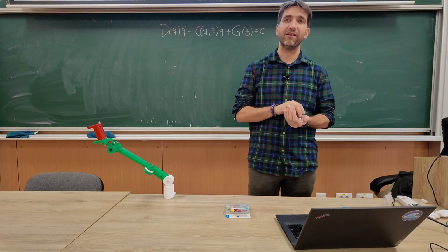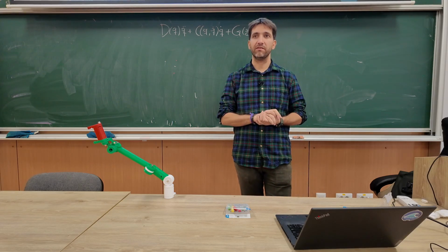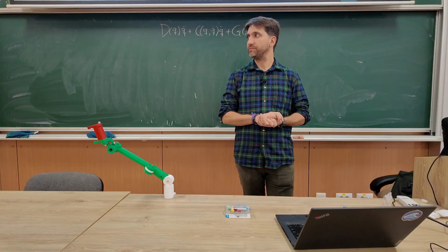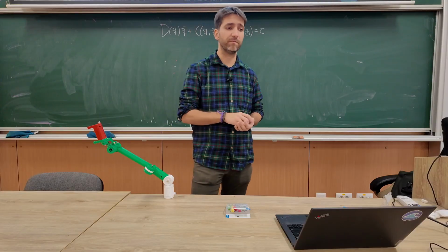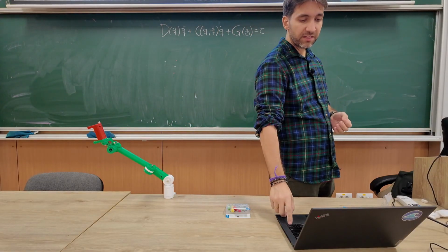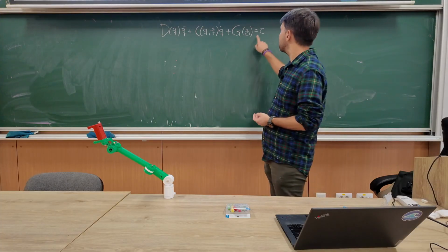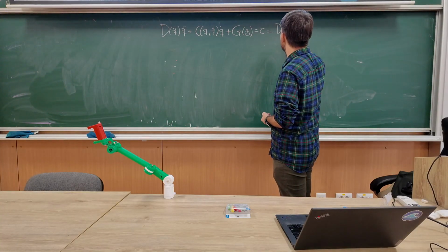Yes. Okay, so we linearize at an equilibrium point. That's what you're saying, right? And then it works. Yes. So that's one way to do system linearization at a specific equilibrium point. But we can do something better. We can basically choose our input torque, so this torque, to be equal to something like this,